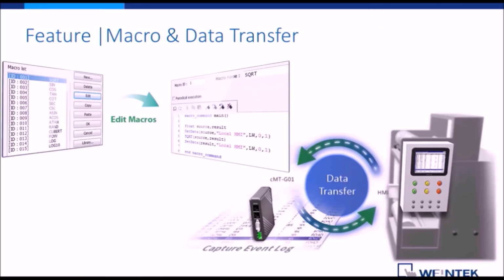Okay. Macro and data transfer is also a big feature we have in our HMI. Macro is what we can use to write short programs to manipulate data. And data transfer is a useful feature for moving data between PLCs. Our gateways can connect to more than 9 controllers, and we can allow you to transfer between them even though they're using different protocols. Even with our gateways, there's no screen to execute these transfers, but you can use a macro to automate to a certain extent.